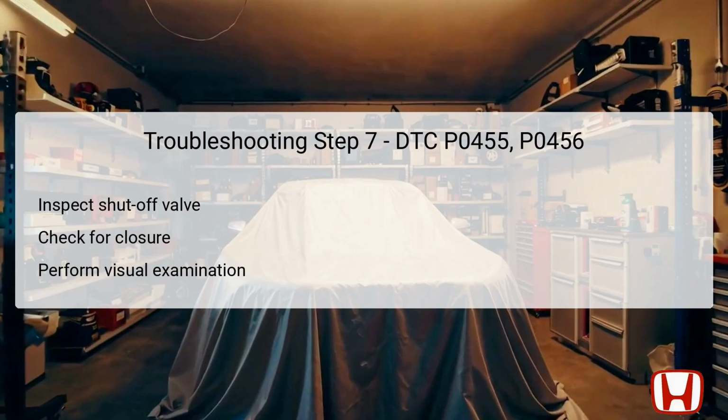Next, focus on inspecting the shutoff valve integral to the main flap unit. It is vital for regulating fuel flow and ensuring the vapor containment process operates without interruption. First, ensure the misfuel inhibit device is removed to allow for a clear view. Conduct a visual inspection to confirm that the shutoff valve remains in a closed position under normal operating conditions. If the valve is found to be open or malfunctioning, it may indicate issues with the main flap unit, necessitating further diagnostics or part replacements.